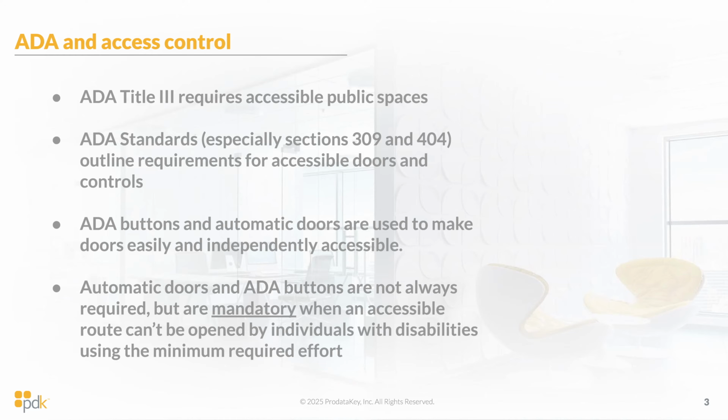ADA buttons and automatic doors are used to make the doors easily and independently accessible. And so there's a whole outline of what that looks like: space available, where the button goes, how easy it is to open the door with how much pressure. But the gist of this is that you don't necessarily always need automatic doors and ADA buttons, but they're mandatory when an accessible route can't be opened by individuals with disabilities using the minimum required effort. Again, that's all outlined in sections 309 and 404, and a few other places as well.